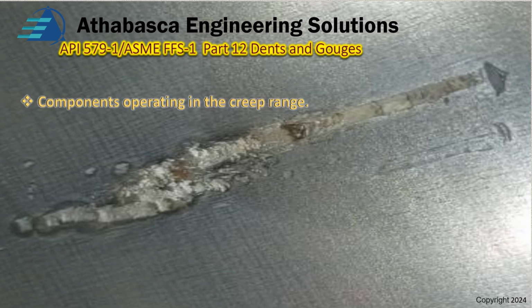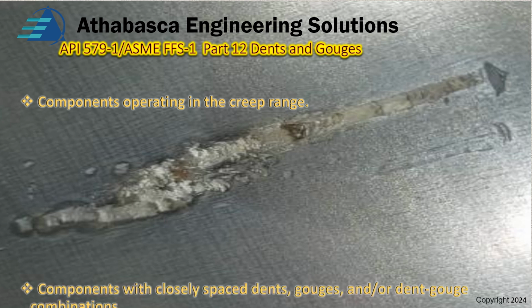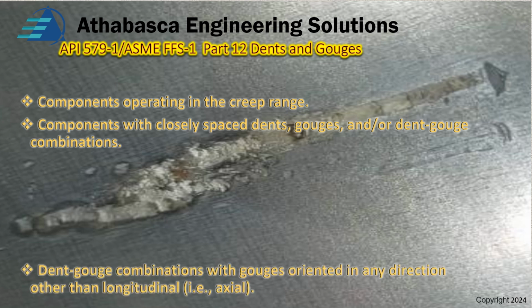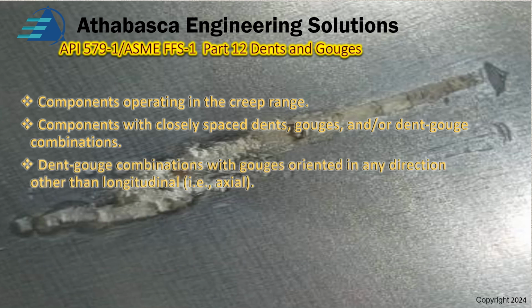Continued. For components that are operating in the creep range, level 3 is required. Components with closely spaced dents and gouges and/or dent gouge combinations also require level 3. Recall earlier with 1 and 2 there were spacing requirements. The analysis could only be done if the gouge was in isolation, which is not always easy.